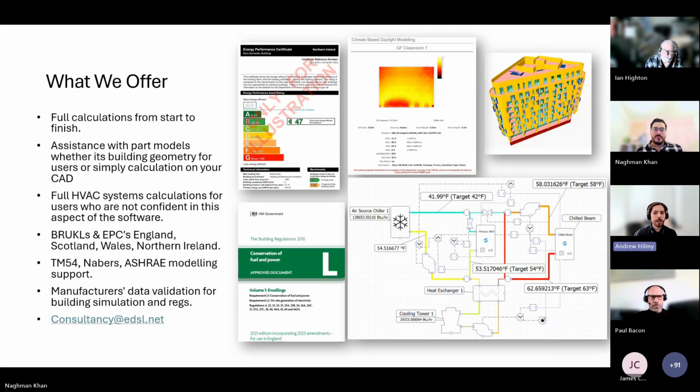For TM54, when you have to model different occupancy scenarios, for example if you've got uncertainty in your occupancies, then you can go back to the TBD, alter your internal conditions to model different occupancy patterns, and then resimulate and generate those graphs quite quickly. Once you change the TBD, all you have to do is simulate your TBD and then resimulate systems, and it will pick up those changes.